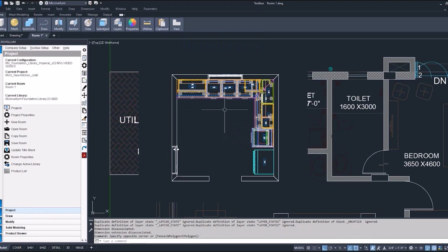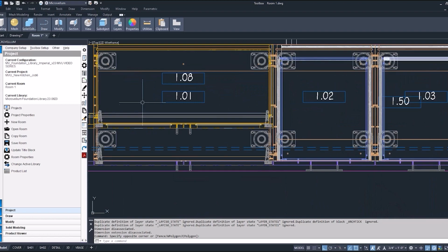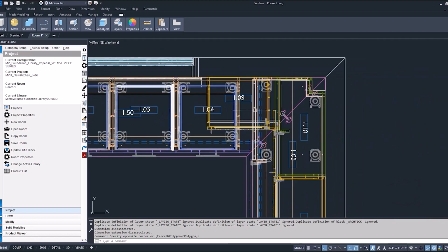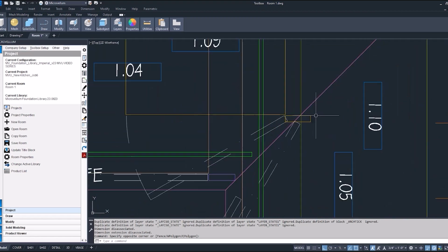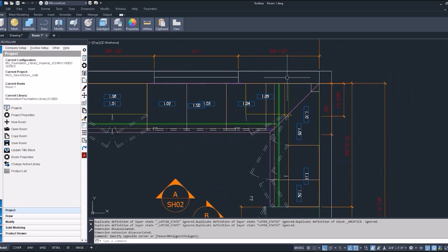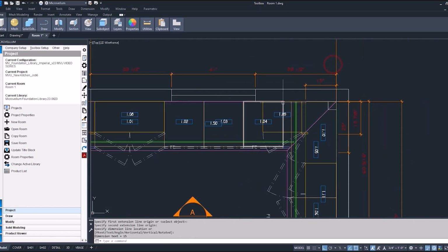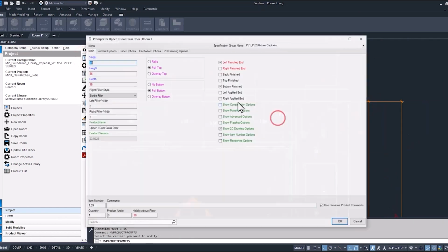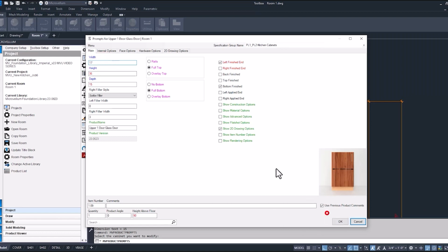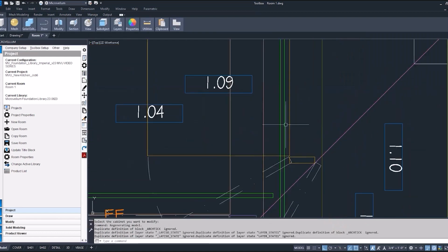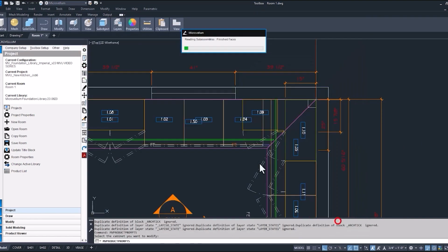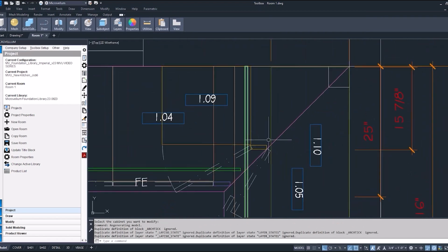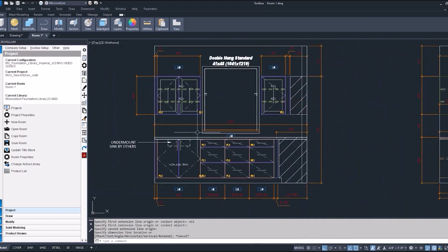Now, after that's done, we want to make sure that we don't need to make any changes to make sure these cabinets are going to work as they go out into production. So it's a little hard to see in this view, so let's take a look at our plan view over here in 2D. So I see a conflict in the corner, and that's because of our upper cabinet depth changing to 15. So why don't we go into that upper cabinet next to the window and take off 2 inches in the width. Because I pulled a dimension, my layer went back to 2D dim. So I'll have to redraw that again. It's better, okay. And then we have that space we need for our blind panel.